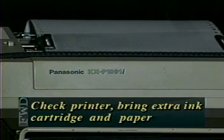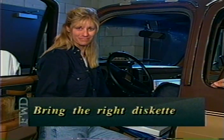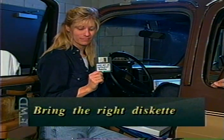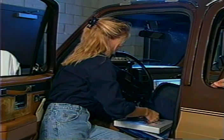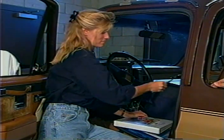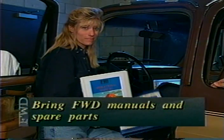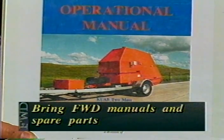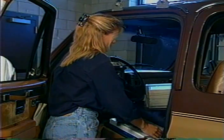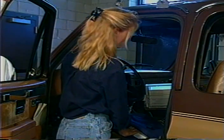Be sure your printer is in good working order and that you have an extra ink cartridge and a good supply of paper. If your FWD has been to the calibration center before, be sure the diskette containing the last set of calibration results is in your van. If this is your first trip to the calibration center, bring a blank formatted diskette with you. Also, be sure your FWD manuals and the most commonly needed spare parts are packed in your van or trailer. The calibration centers are not FWD repair garages. They don't stock spare parts.